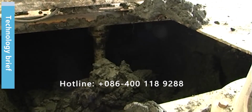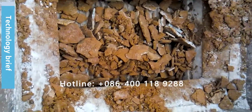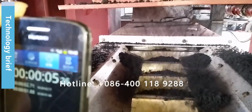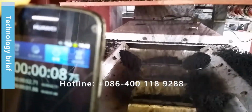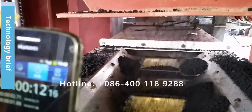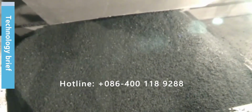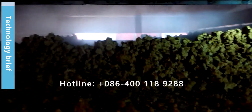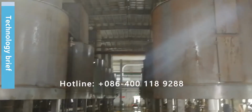During the drying process, the sludge is dried directly into porous particles, with water content as low as 3%. The granulation dryer has the specifications of high energy saving, low maintenance, and quick assembly. Depending on the sludge specifications, the granulator consumes electric power between 1 kilowatt and 1.5 kilowatt per ton of sludge, and the dryer consumes saturated steam between 1.05 and 1.1 kilograms per 1 kilogram of evaporated sludge water.